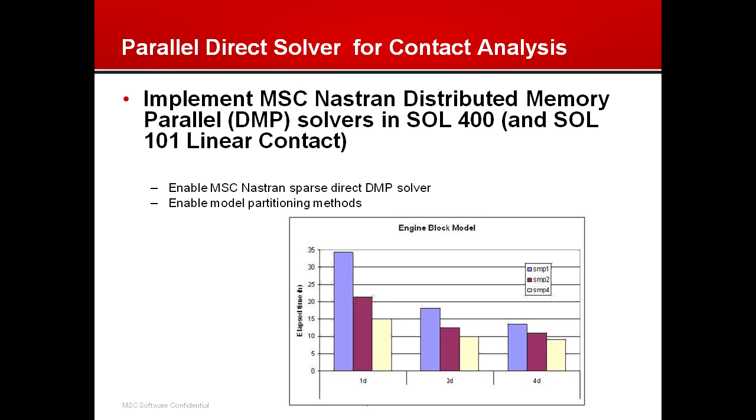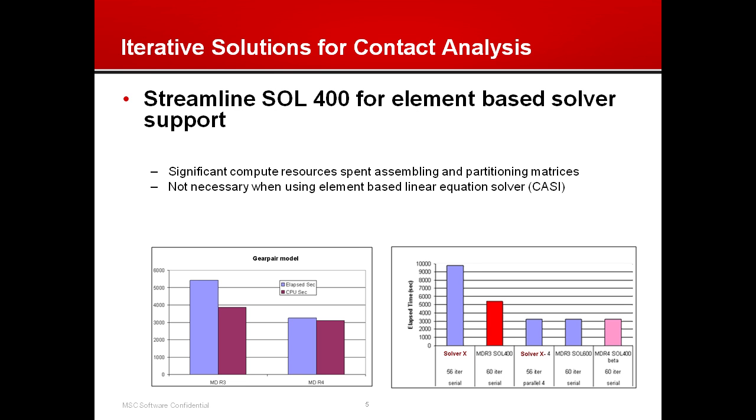So what you can see is effectively using a combination of distributed memory processing between 1, 2, and 4 domains, or even a greater number of domains, and in conjunction with that, using shared memory processing, we can see a continuous reduction in the total time to perform a simulation. And what we're doing always in this process is we're really looking at total times. We're not just looking at the solver time. So that includes things like the input and the output, which is difficult to parallelize.